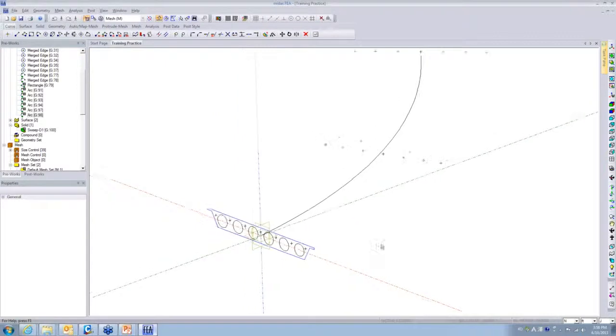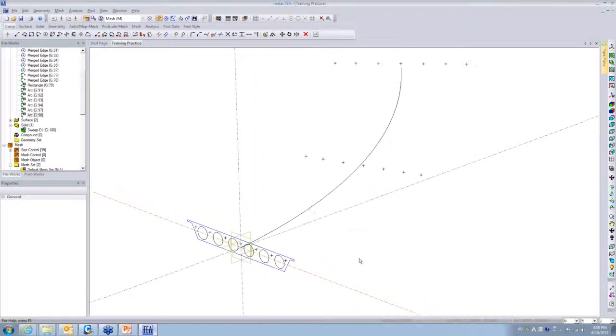Simply, you can generate the solid elements here, or if you want to model it with the plate, you can do it with the plate. But I recommend, if you want to do it with FEA, go with solid for a more accurate result, because the analysis time doesn't take much longer with plate or solid in this simple model.